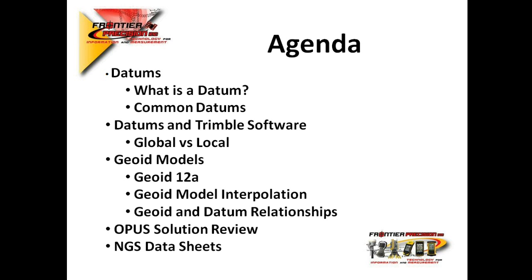and Geoid model interpolation. Some of you may know what that is, some of you may have no idea what that is, so we're going to cover that from top to bottom because that has also been introduced into the Trimble software as of late. And then we will discuss geoid and datum relationships as they relate to each other and give you some recommendations that we've received from some of the NGS personnel in regards to how the geoids, specifically Geoid 12A and Geoid 2009, relate to the different datums that are out there or realizations within NAD83.